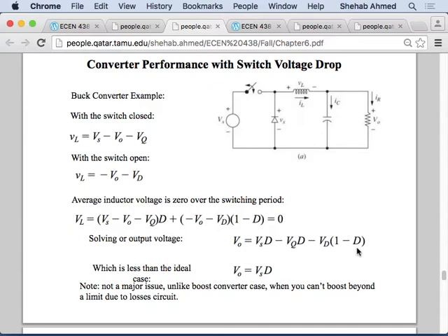Reduce the voltage even further, right? But I have a buck converter, so it doesn't really matter, right? That's why the effect on the boost converter was more important, because in the boost converter it actually limits the boosting ratio. But here it doesn't limit the physical phenomena I'm trying to achieve anyway, right? It's going that same direction, right?